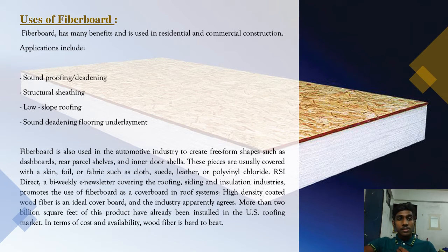Okay, the next one is uses of fiberboard. Fiberboard has many benefits and is used in residential and commercial construction. Applications include soundproofing or deadening, construction sheeting, low slope roofing, and sound deadening flooring underlayment.